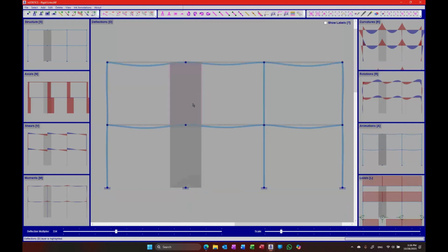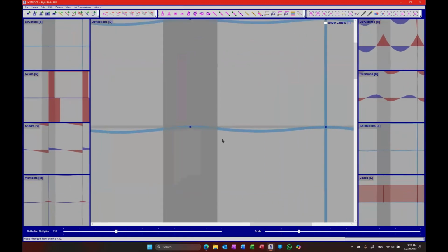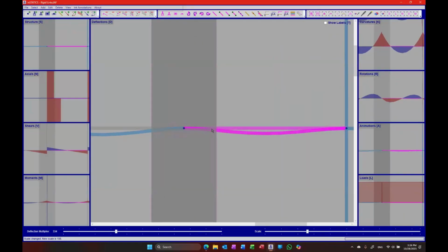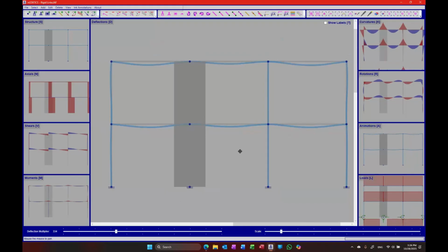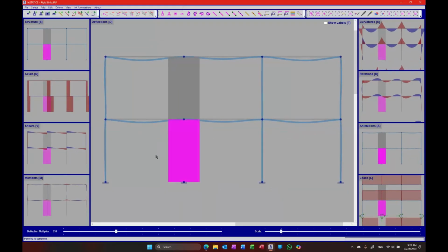Take a look at the deflected shape here also. You can see that this element is actually deforming down even before it comes out of that virtual area inside the shear wall, which is also not the real behavior. So there's something wrong here, or something not so accurate, but it seems like we can't really handle it with our frame elements, because these are frame elements.